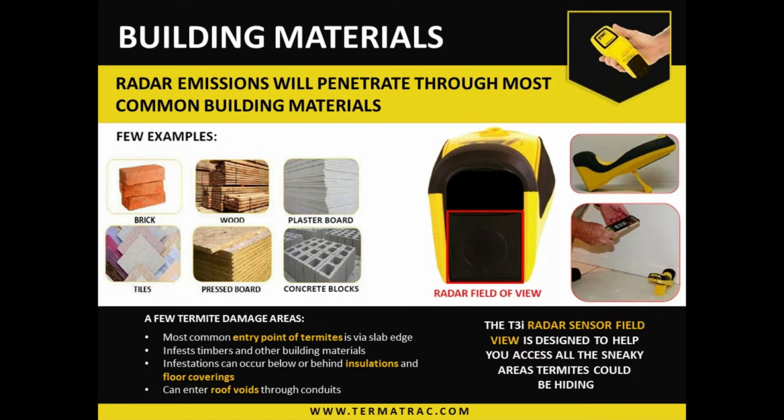As we increase into more dense material, hardwood types, the penetration does reduce quite significantly, and it will almost halve that of a pine product or a softwood product. So in tests we did here with some native hardwood slabs, we're only achieving around the 40 to 45 millimeter mark of penetration.